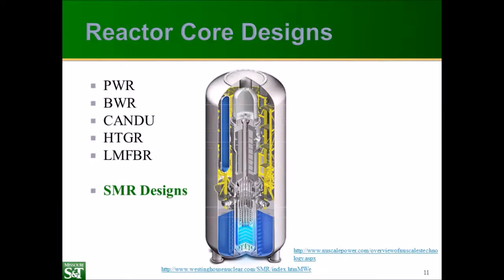Small modular reactors are a pretty recent development. Over the last few decades, people have been looking at designing very small reactors to use for microgrids and other systems. Westinghouse is designing a reactor. Initially, they were involved in the IRIS consortium, but they left to design their own based on AP1000 technology. We have a shortened core height here, but the RPV is still full height to allow for natural circulation during accident conditions. But the heat transfer behaviors are very similar.